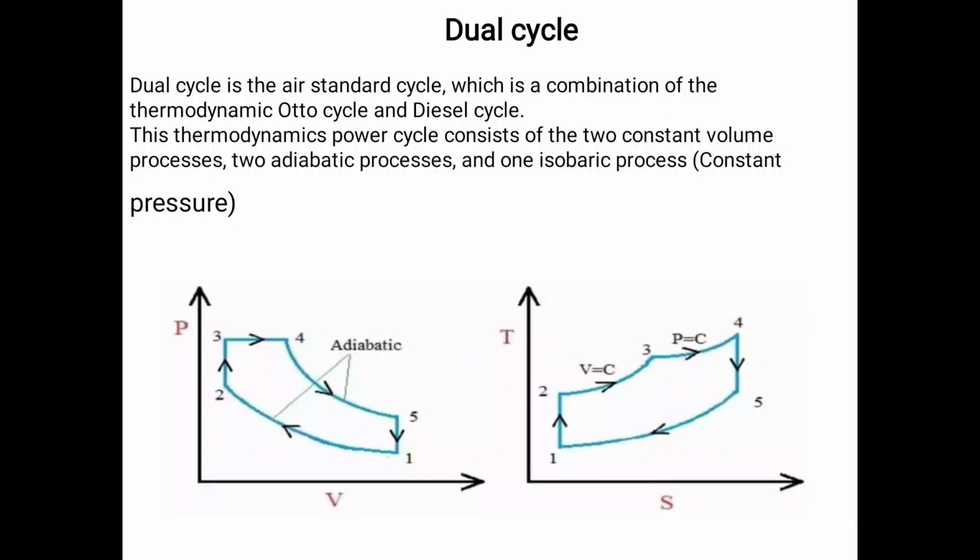of the compression stroke. From this diagram, the air is compressed isentropically from condition 1 to 2. The heat is supplied to the compressed air partially at constant volume and partially at constant pressure until the air reaches condition 4. The air expands isentropically until it reaches condition 5. The heat is rejected by the air to the external sink at constant volume until it reaches condition 1 and the cycle repeats.